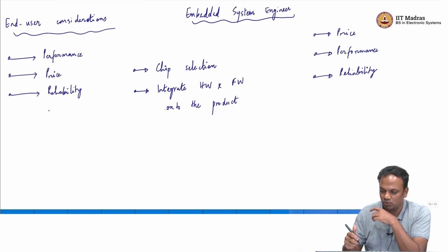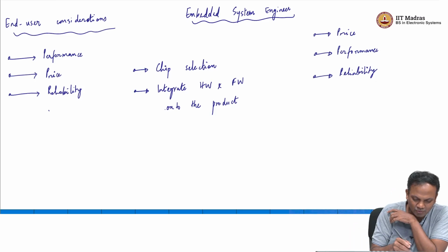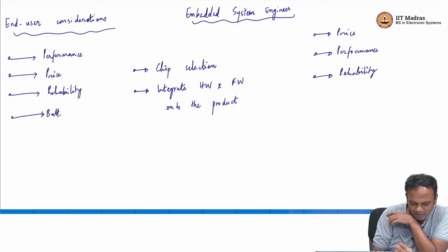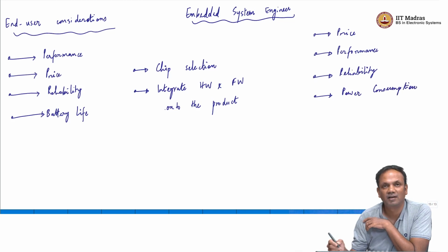So, in addition to price, performance, reliability, what the user will also care about is battery life, which means that what the embedded system engineer needs to care about is power consumption, because power consumption correlates directly with battery life.